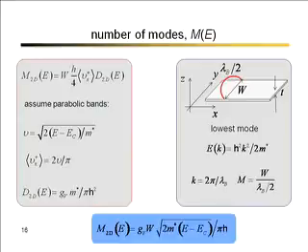And then I can determine how many half wavelengths will fit into the width. Because at a given energy, I get a K, which means I get a wavelength. And then I can find out how many half wavelengths fit into the width of that transistor. Every one of those is a conducting channel. So that's why this quantity M is called modes, because people thought in analogies to waveguides. You know, how many modes do you have in a waveguide? We think of each one of these modes as being a separate conducting channel. So given an energy E, then we can find out how many channels are there at that energy. Each one can conduct current.